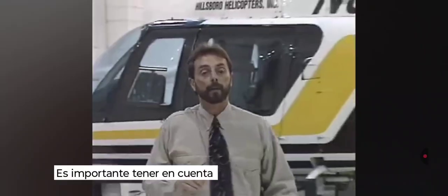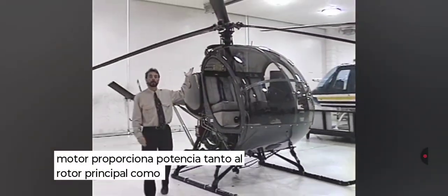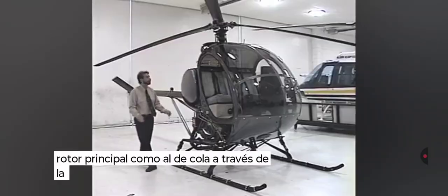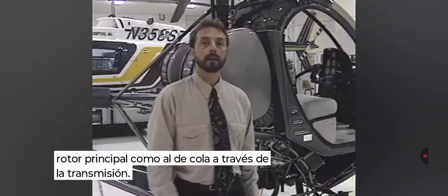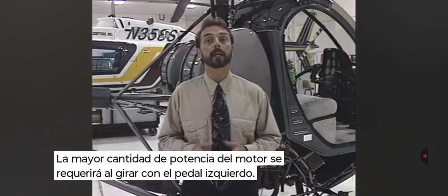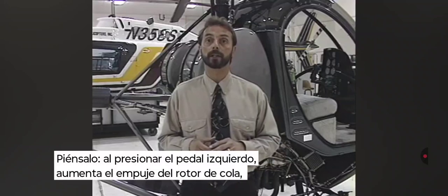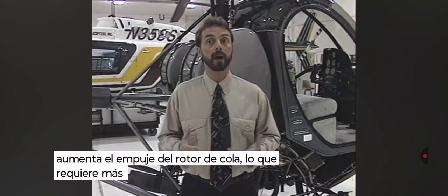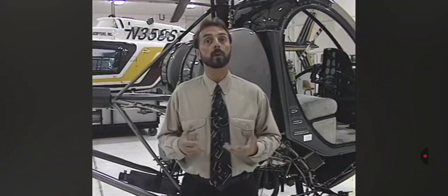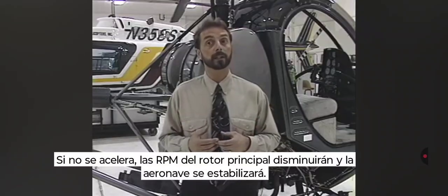It's important to keep in mind that the engine is providing power to both the main rotor and the tail rotor by way of the transmission. The greatest amount of engine power will be required when making a left pedal turn. Think about it. Pushing left pedal increases the thrust of the tail rotor, thus requiring more power from the engine. The main rotor RPM will decrease and the aircraft will settle if throttle isn't added.